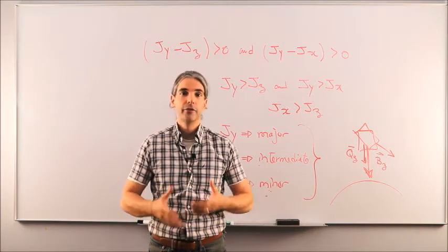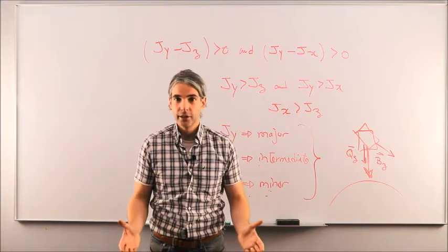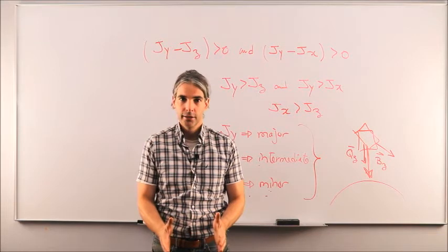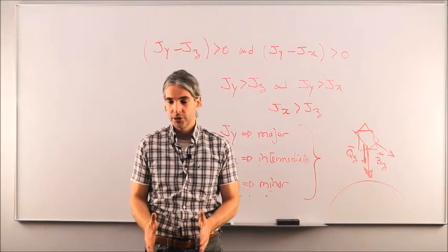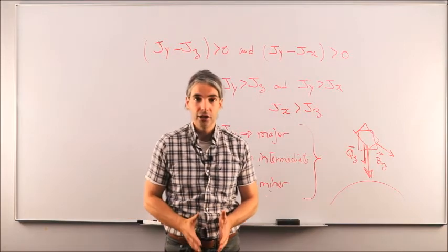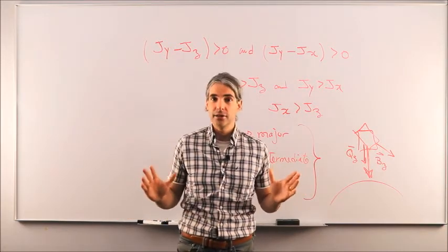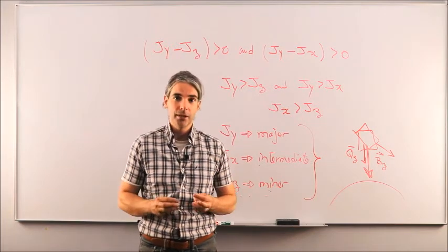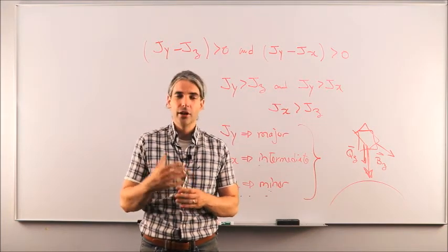Okay? If you require for your particular application a much tighter pointing accuracy, say you want a spacecraft to be always within 0.5 degrees of a desired direction, then forget about passive attitude stabilization techniques. Those techniques are free, easy to implement, but the accuracy you get out of those is kind of coarse.